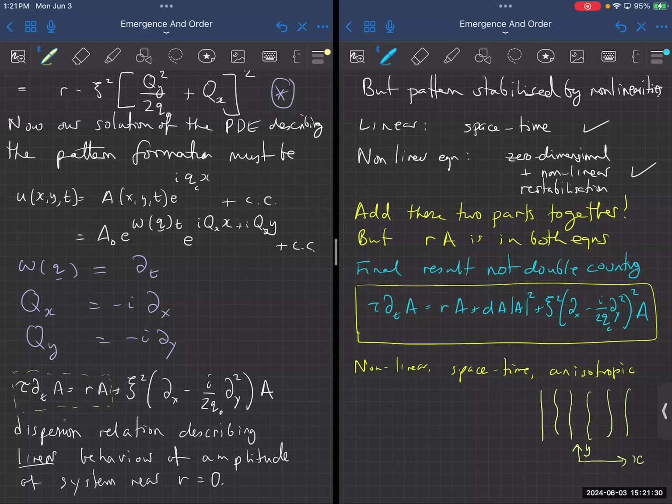It has energy. When you bend a beam, you're inducing curvature. The curvature is d2y by dx squared over some first derivatives squared. The energy of a beam shouldn't depend upon which way I bend it, so it's got to be proportional to the curvature squared. So it's going to be a fourth derivative of the displacement. Engineers know that, and you can derive it in a much more textbook way than the way I just told you, but that's the quick and dirty way to do it. And so you would expect it to be d4 in the y direction, and then in the x direction, you think things are going to diffuse, and there's going to be some cross terms.